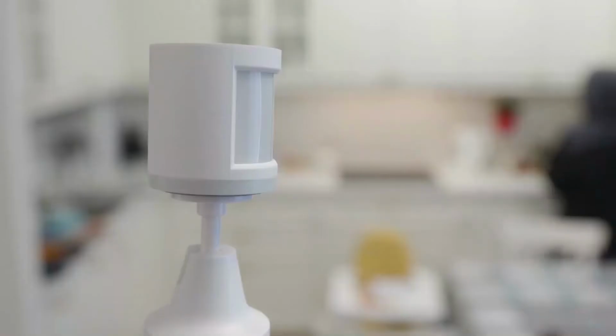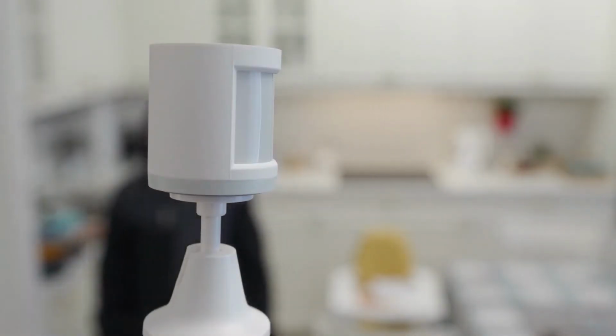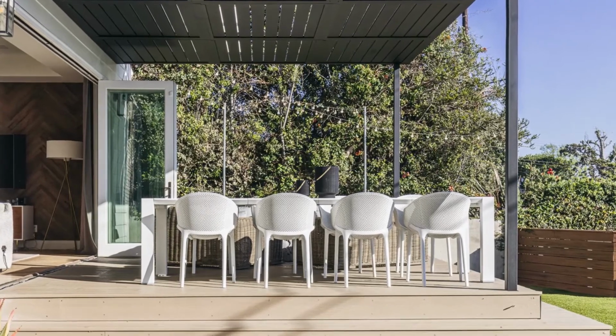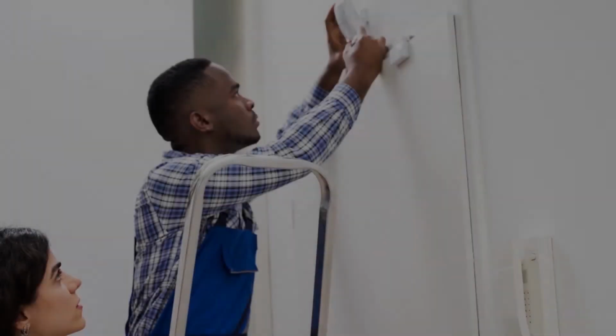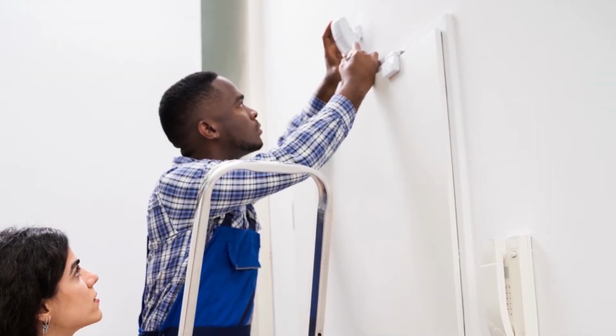Motion sensor. A motion sensor is a device used for both the interior and exterior areas of your property to detect nearby people or objects. When installing these sensors, there are two things you should be mindful of. 1. Be sure to install the sensor at the recommended height, as too close to the ground will result in too little coverage, and too high will result in the sensor not detecting objects when they enter the covered area, even if the sensor is pointing in its direction.